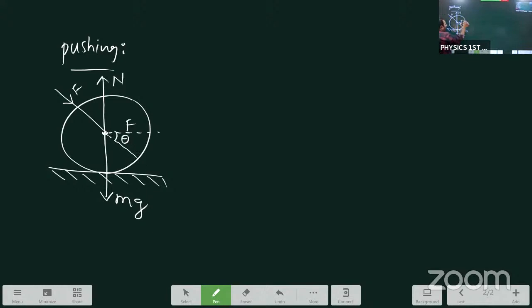One is F cos theta, the next one is F sin theta. The previous case mg and N, and the present case, both are the same. The reason: normal reaction always balances with weight in the upward direction, and gravitational pull always acts toward the center of the earth. So the arrow marks differ: F sin theta downwards, N and mg.